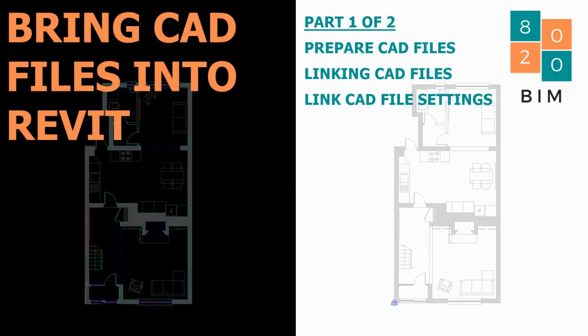The next part of this video is going to go through how we can control the CAD layer visibility and presentation in Revit itself, and basically how we can control what we see from the CAD data in the Revit environment. Then we're going to quickly talk about in what instance you should consider importing CAD data over linking CAD data, and that will lead us through to creating standard details that you may have from AutoCAD in Revit.